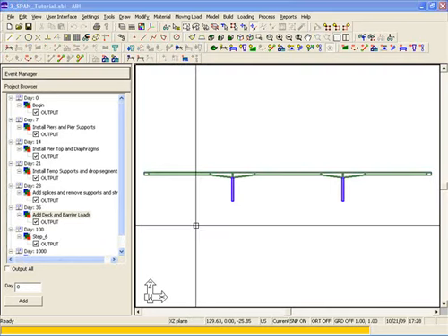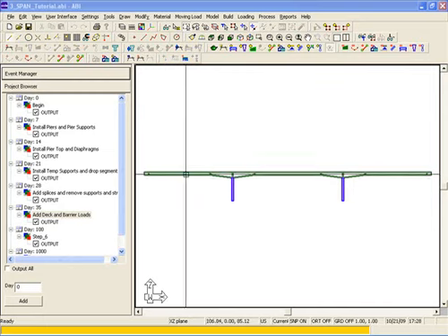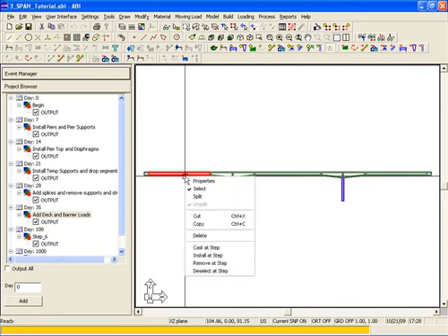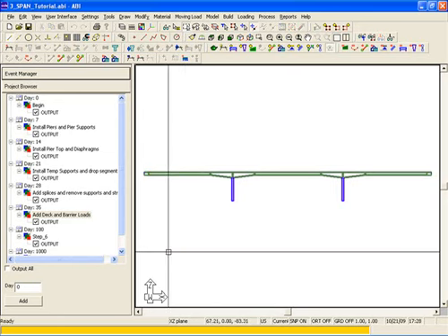It's also important to note that any segment, either horizontal or vertical, can be cast at a day as well. If we select a segment and right-click, we can cast at a certain step. This allows the aging process for the concrete to begin prior to installation. If we install a step without the cast command, the installation and casting begin at the same time.